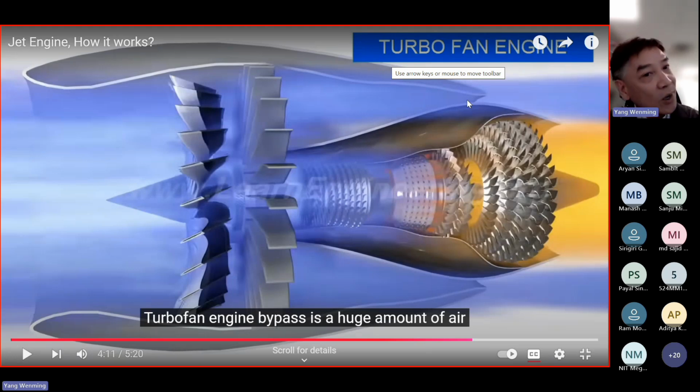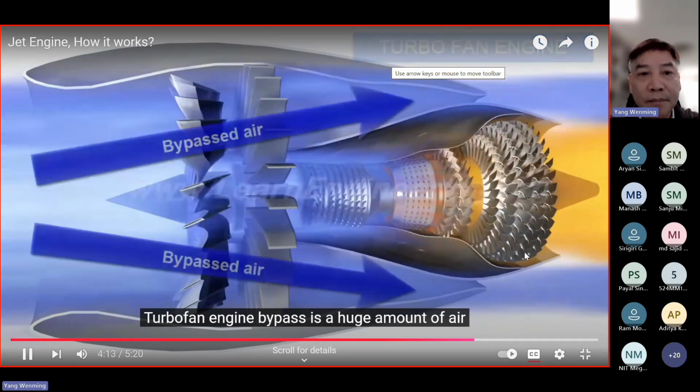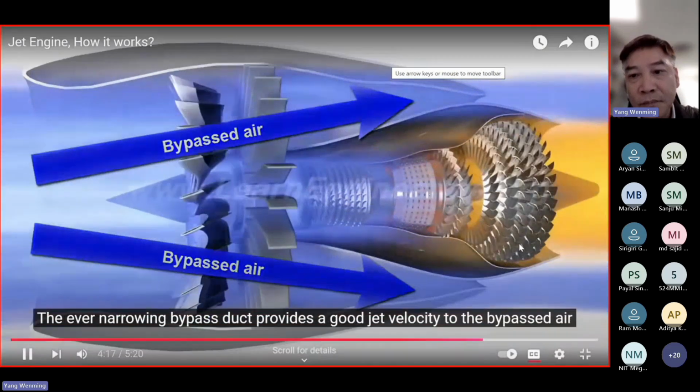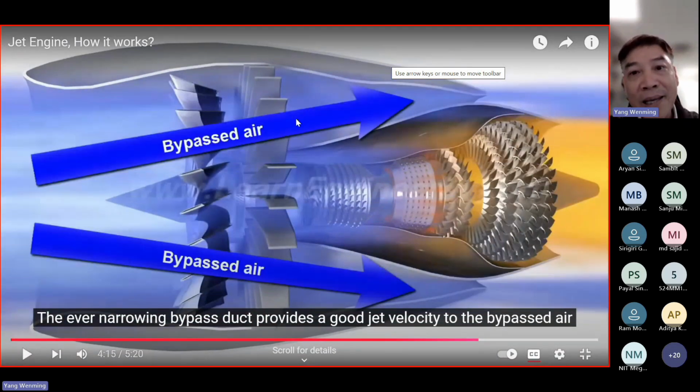So anyone knows the reasons why it is designed like this? You can see here, about 80% will bypass and not attend the combustion process, and only 20% will flow through this multi-stage compressor, combustion chamber, and turbine, and participate in the combustion process, correct?